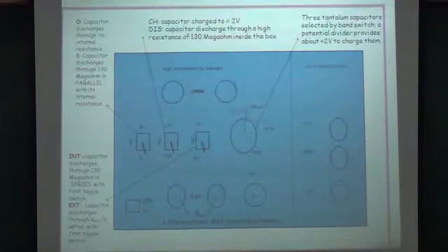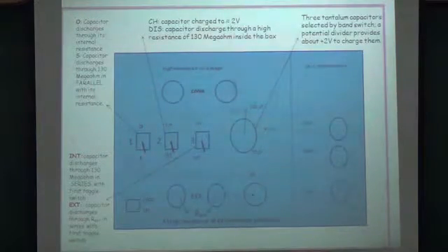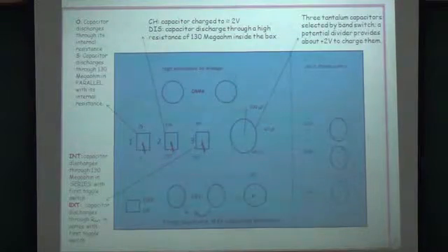Okay, so this is what you will do in this experiment. You are going to first select a capacitor, let us say it's 100 microfarad. You put it to charge, you switch it on, wait for 2-3 minutes, let it charge, and now you have to switch it to discharge. But before you start discharging, you must have a ready stopwatch in your hand, because you have to find out the voltage here, because this is a digital multimeter. The digital multimeter will measure the voltage across the capacitor as a function of time. Time will be measured by stopwatch.